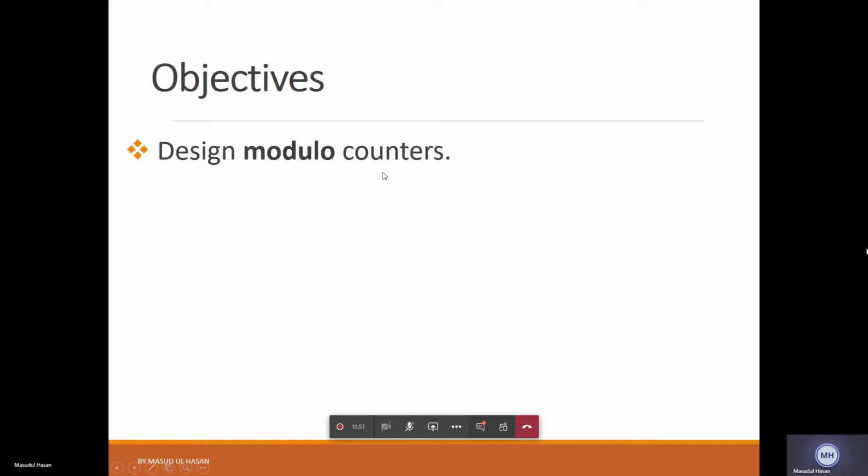Modulo 100, 3 inputs, clock reset CE, and 2 4-bit outputs. Here you can see D0 4-bit, D1 4-bit, and 1 final output CEO. In this simulation, I just got output from here for demonstration, just to show you. But you don't need it. You just need CEO.